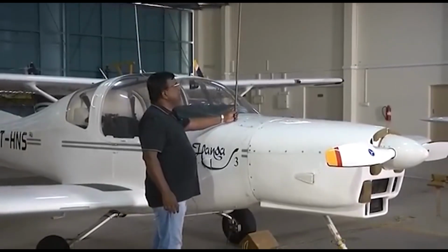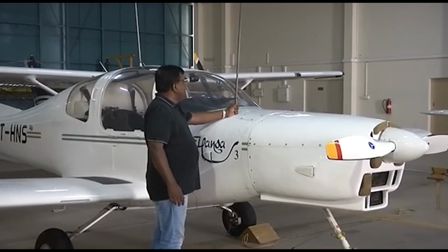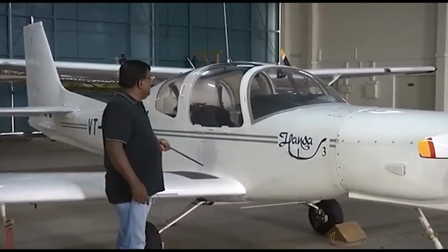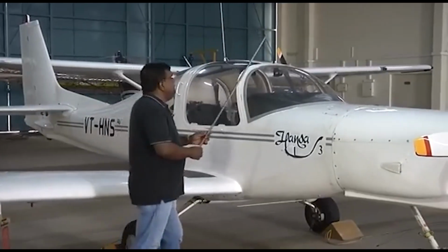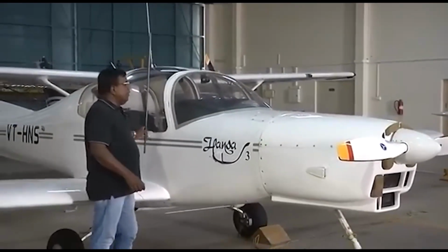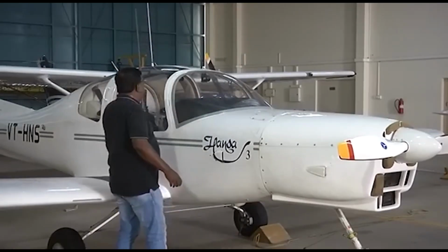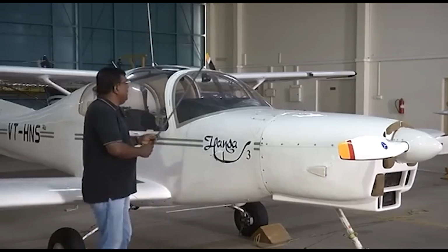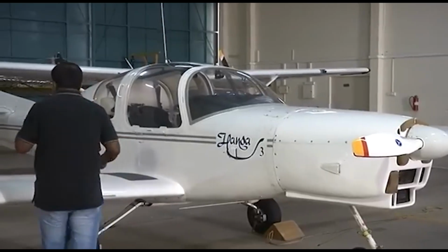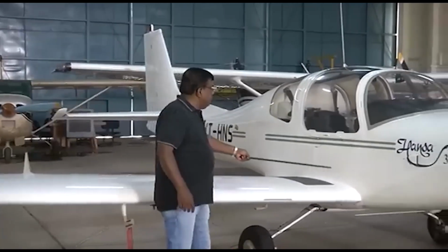Okay? Let us take the example of lift. For a small angle of attack, if this is the lift direction, but I am writing the equation of motion assuming the whole mass is at the center of gravity somewhere here, then I need to transfer this force from here to the center of gravity. And once I transfer a force from here over a distance, I know that I can transfer it with the force as well as a moment. Okay? So I am putting, because of this fuselage, there is one force, which is lift, and a moment. Similarly, take the case of the wing. So there will be a force, the lift force. I again transfer it with a moment to the CG.